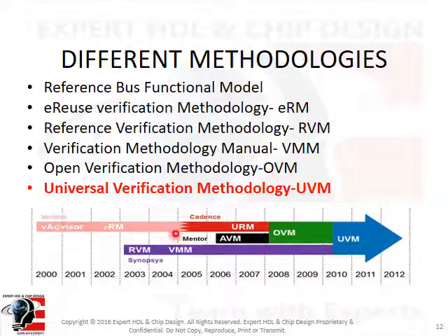Having different methodologies in the industry led to a lot of issues, especially for complex SoCs, which might use many different ASIC IPs developed using different methodologies. Hence, the industry collaborated to create one common powerful environment. The UVM class library brings much automation to the SystemVerilog language, such as sequence and data automation features, and unlike previous verification methodologies developed independently by simulator vendors, is an Accellera standard with support from multiple vendors like Aldec, Cadence, Mentor, and Synopsys. UVM is a methodology for functional verification of digital hardware, primarily using simulations.